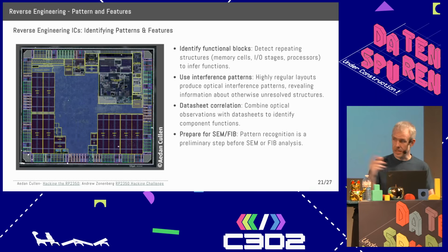The colors that you see on the chip are created because of the pattern of the transistors and the metal layers. And therefore you can identify which are similar structures. Here you can clearly see memory, and if you check the data sheet, you can guess, depending on the size of the memory, how many kilobytes it is, which area is which, and you identify over the chip where the CPU or the main part of the CPU is, where's memory and all the peripherals and all this stuff.